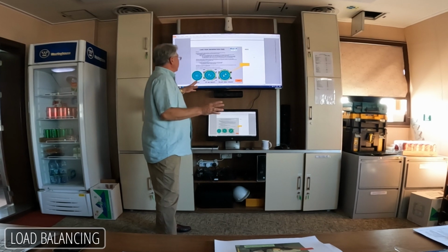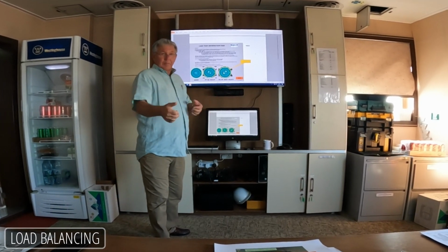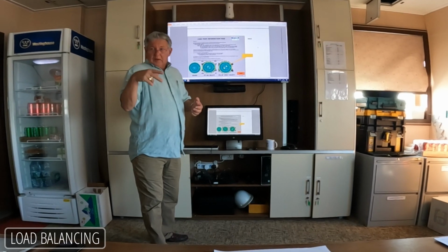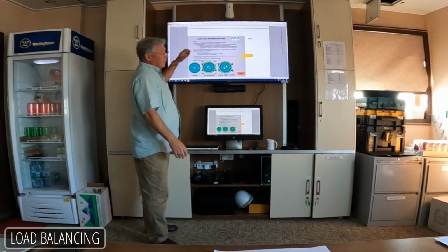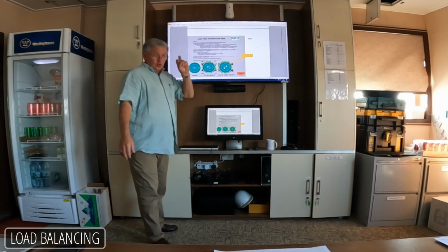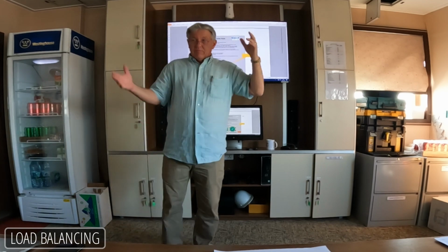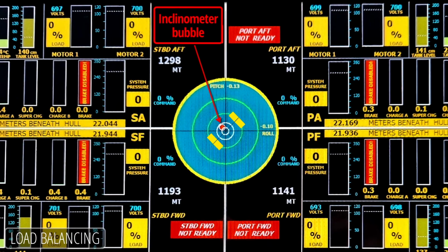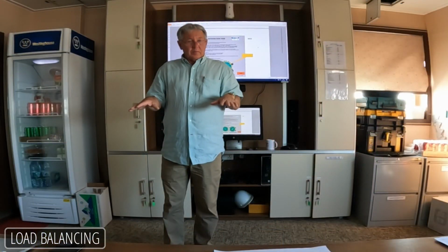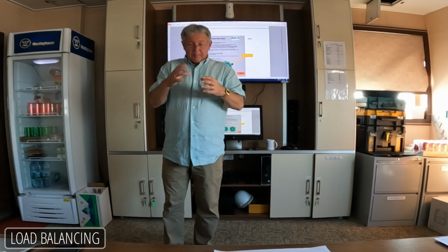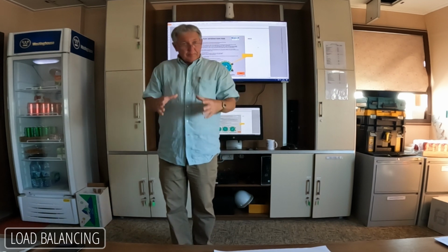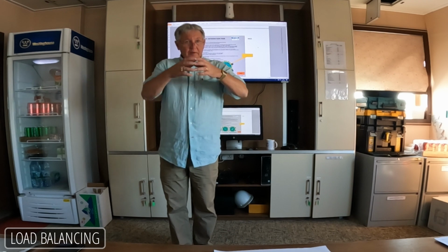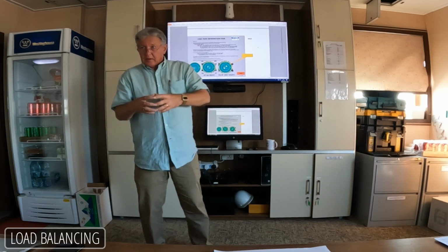I decided that it would be best to assist the operator so that he can see this instead of doing the math. It's very important to always jack the vessel in the best trim possible. Trim means 2 things. Vessel trim, keeping the inclinometer in the middle. Because when the vessel's trim, the legs, if they've been properly stomped and properly preloaded, have a tendency to stay more comfortably in the tower. They're not being side loaded.